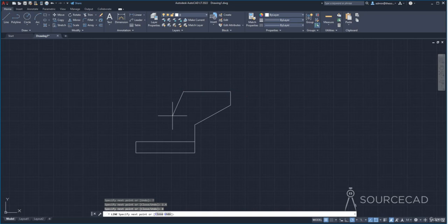Now the process will be exactly the same. Simply type this angle sign and then type 150 and press enter. There we are. Now again it will be locked to an angle of 150 degrees. With that angle, you can now create it. So let's add a distance, which is 6 in this case, and press enter. So we are done.